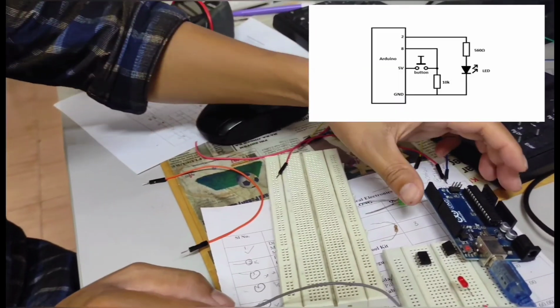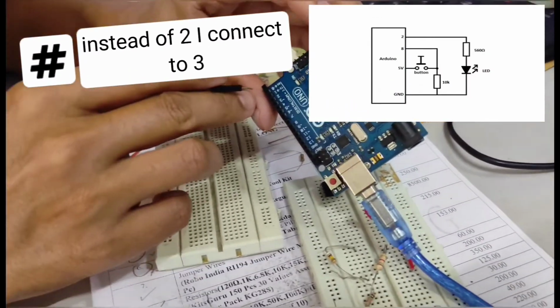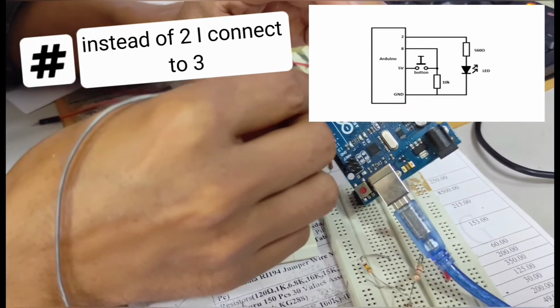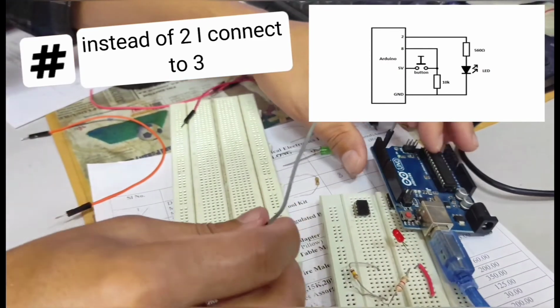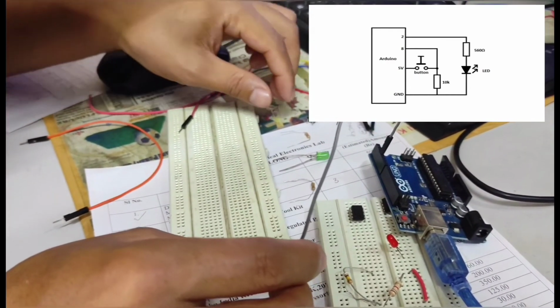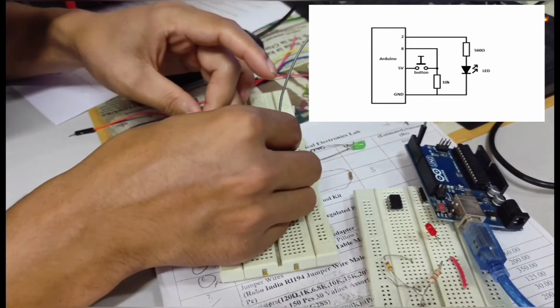First of all, we will connect from pin number 3 of the Arduino, 0, 1, 2, 3. From pin number 3 of the Arduino, it will go to the 560 ohm resistor. So this is 560 ohms. I will put it here.